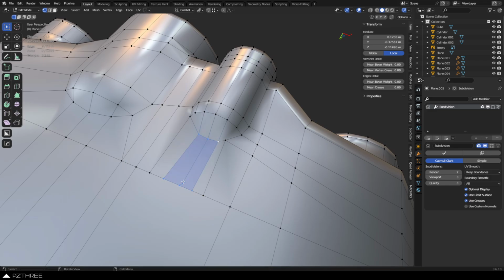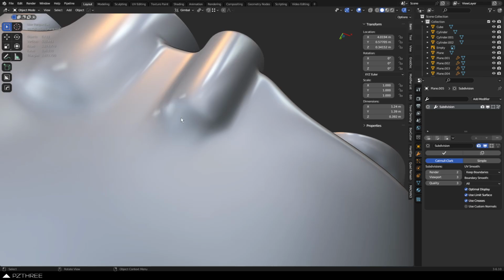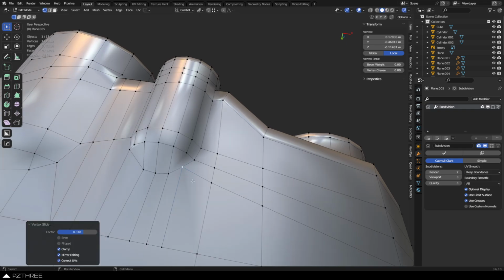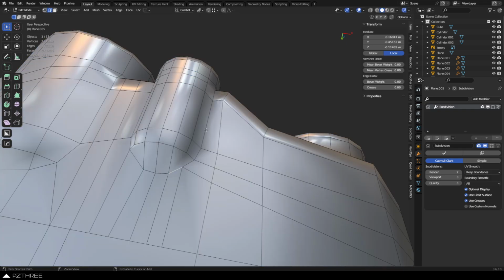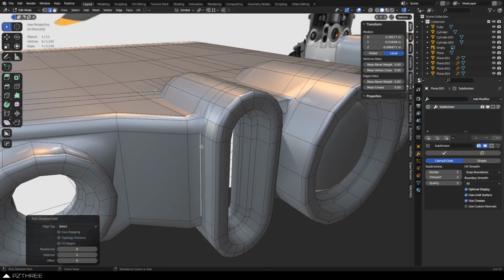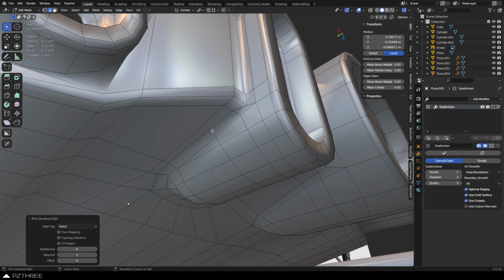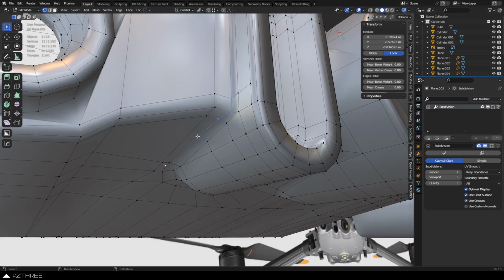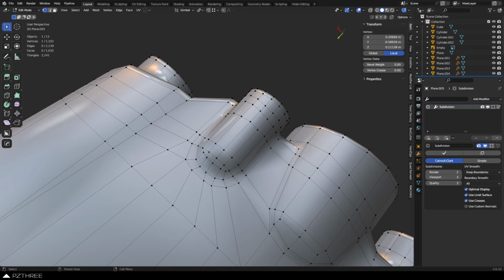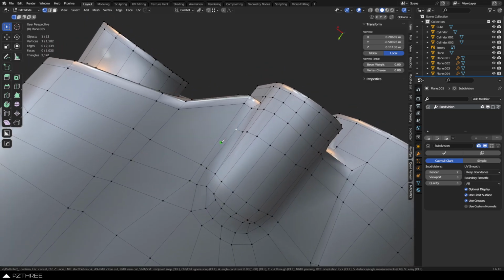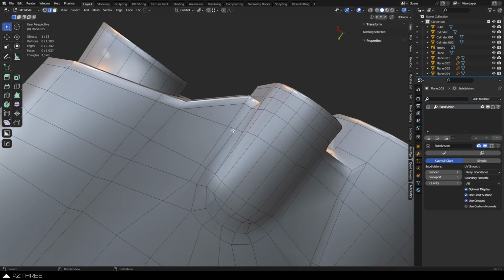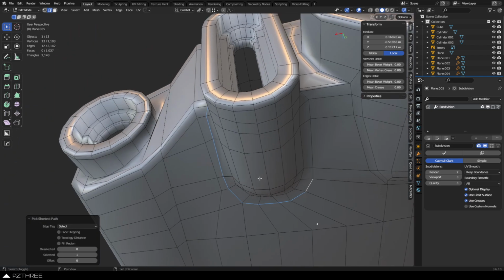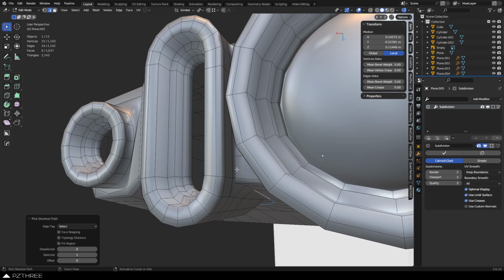Missed that one. Let's go. Okay. So you can see still it's not looking too bad, but it's not maybe as good as we want it. This whole area here, I'm going to control click around. I just want to show you this. You can do this one if you needed to. You see we softened it all back here already. We got an N-gon right there, apparently, that I did not deal with. I'm going to run it into a triangle just for the time being. But if we control click around here, we got everything working at least.